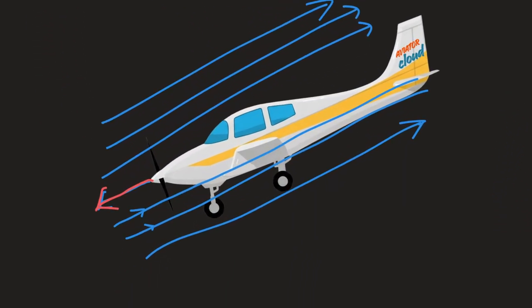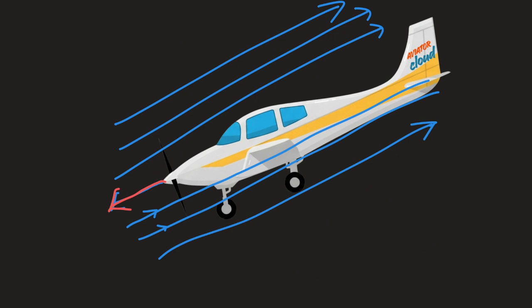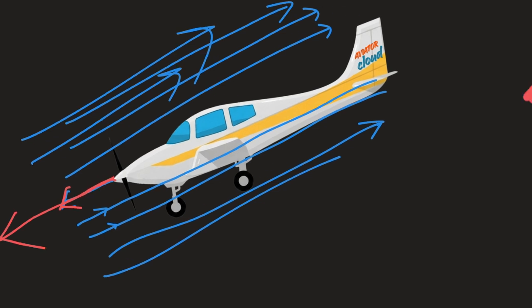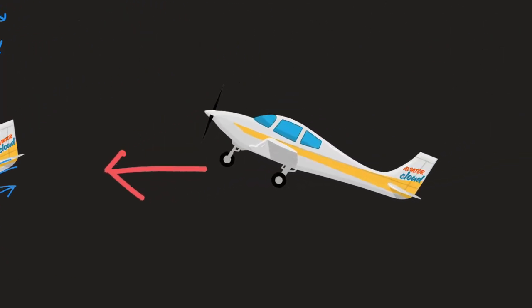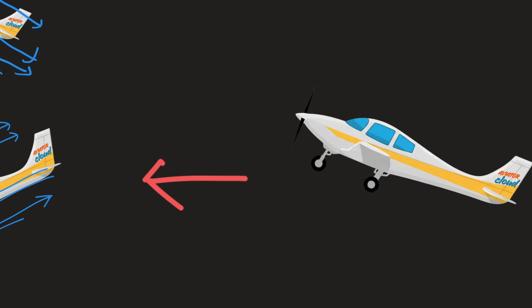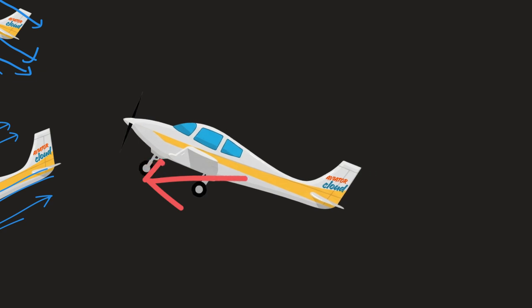Now if this aircraft is descending, where is the flight path? The flight path is like this. It is descending. So relative airflow is always opposite. You have to consider the flight path. Now you can see this image. This can be a little bit confusing. Where is the aircraft nose pointing and where is the flight path? For some reason, this aircraft can move like this. Let's say this is the attitude, toward upward, but the flight path of the aircraft can be like this.